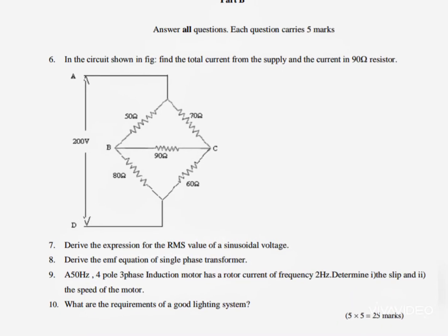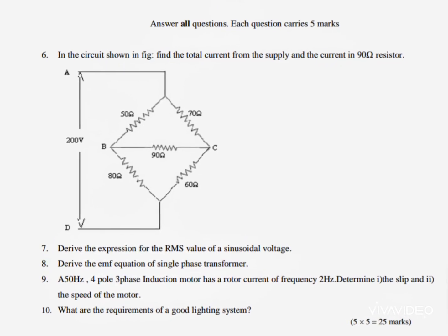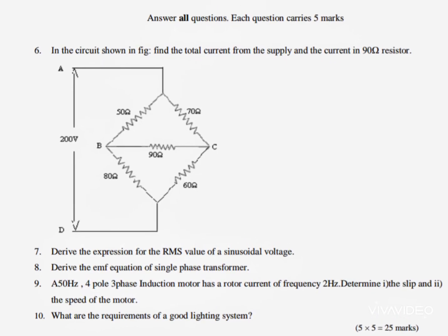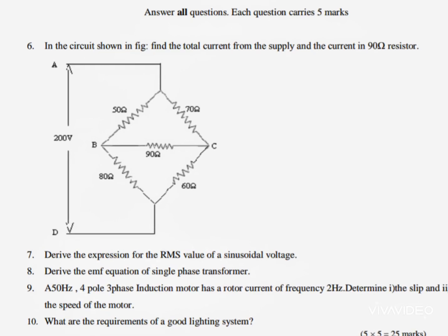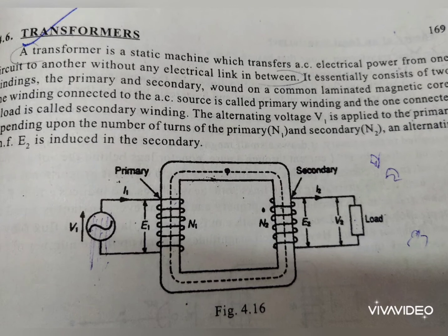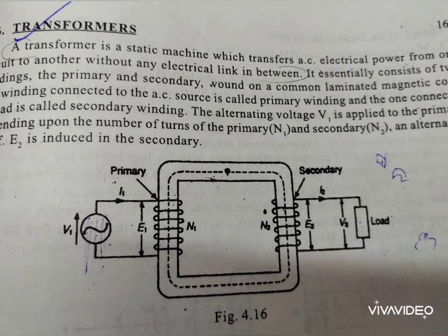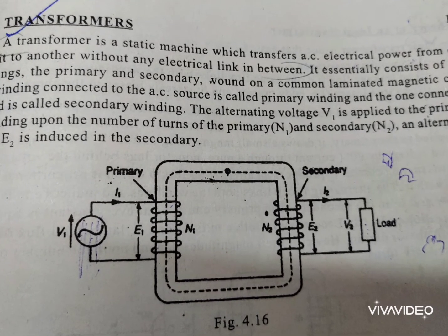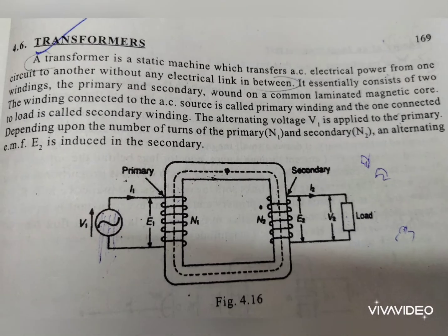Eighth question is, derive the EMF equation of a single phase transformer. So what is a transformer? A transformer is a static machine which transfers AC electrical power from one circuit to another without any electrical link in between. So what is the working principle of a transformer?